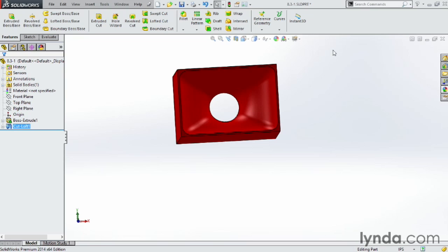Keep in mind, when you do change these values or you make lofted cuts, these are freeform surfaces now. So they're very difficult to define on a drawing or to relay to manufacturing. It's mostly going to be something we'd use to do like some type of a molding process or a casting process.